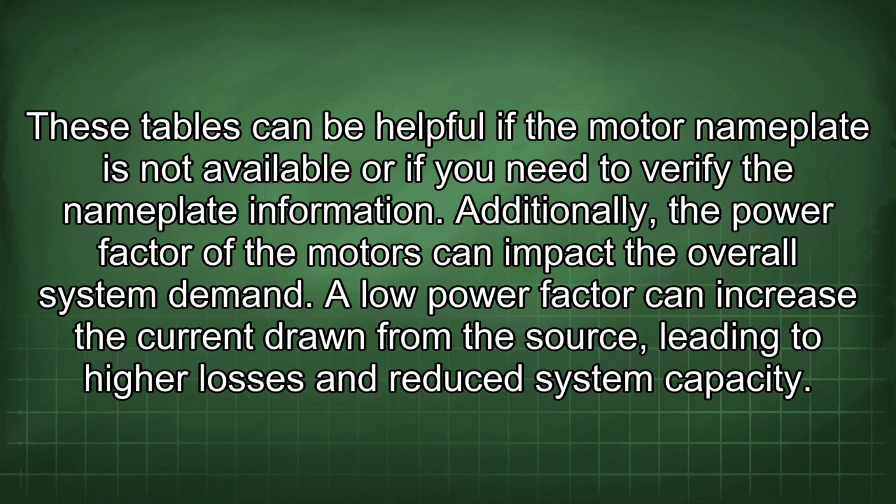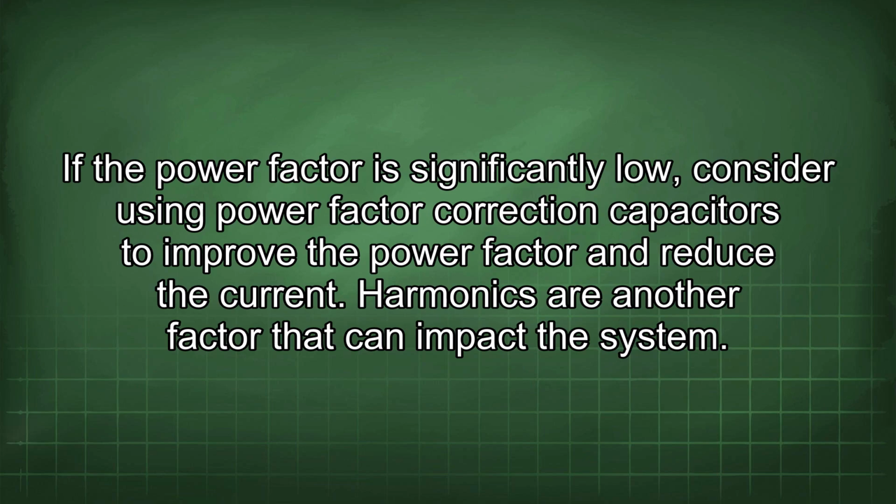A low power factor can increase the current drawn from the source, leading to higher losses and reduced system capacity. If the power factor is significantly low, consider using power factor correction capacitors to improve the power factor and reduce the current.